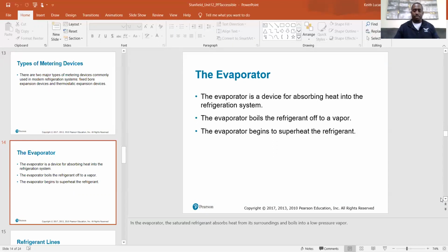How? Because the same heat exchange is taking place, the heat transfer. Inside, on the indoor coil, the warm air from the room is being absorbed into the cold refrigerant, and then the same air is coming out the other side cold.